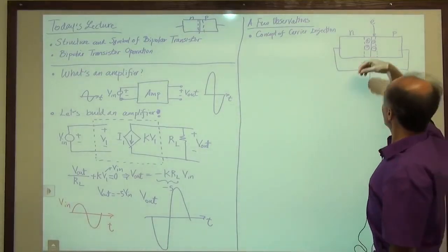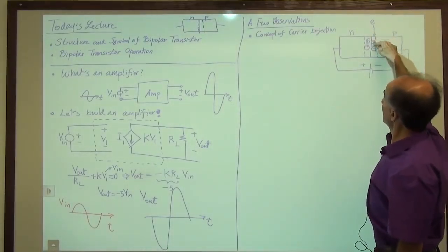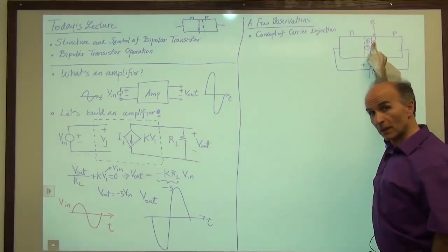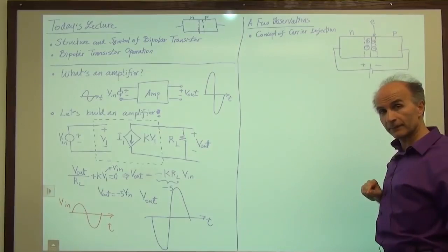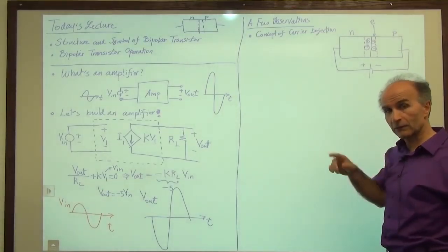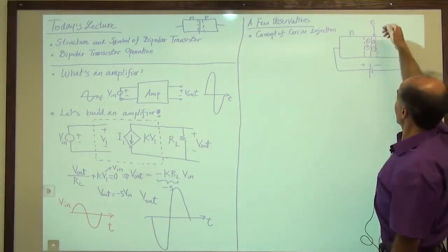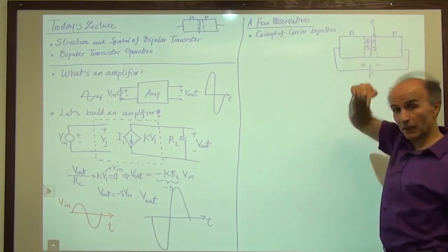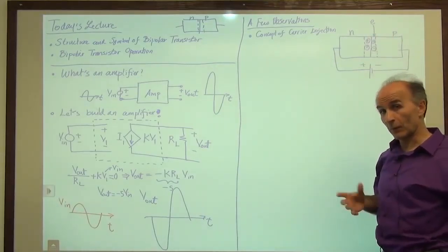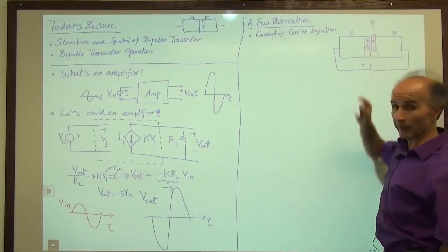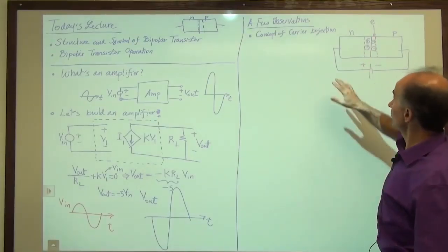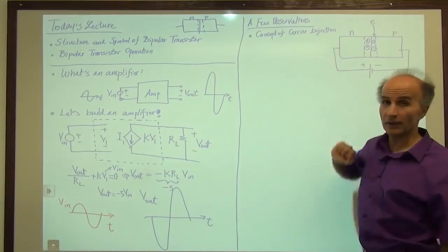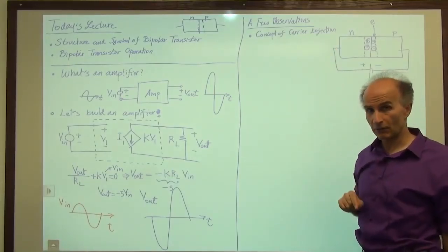So if we keep injecting electrons into this region, they keep flowing through the N side and go to the battery. We have a continuous current flowing at all time as long as we have electrons supplied into that region. Now, we don't exactly know how this is possible from outside, but that's okay, we'll get there. So this is what we call carrier injection into the depletion region.